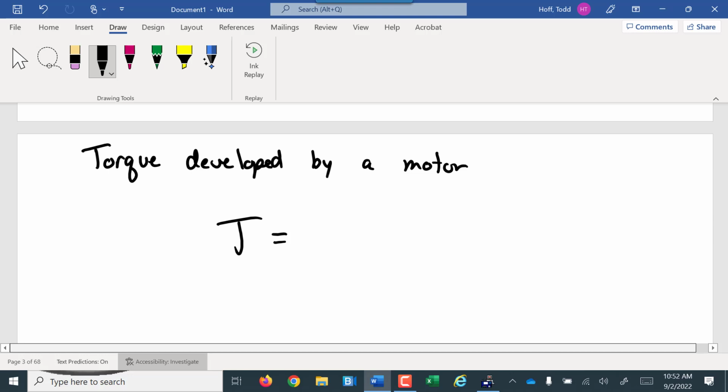No, 746 watts is electrical horsepower. I blanked out on the conversion between foot-pounds and horsepower. But the constant 5,252 comes from that conversion of the amount of foot-pounds in a horsepower times your horsepower. And then for most motors, it depends on the RPM they are running.